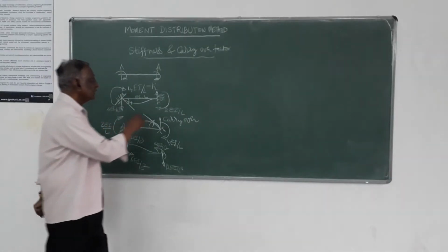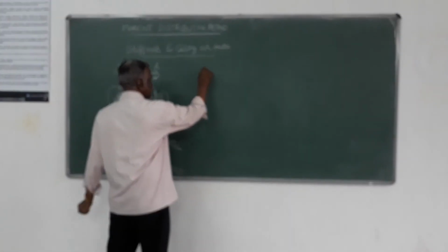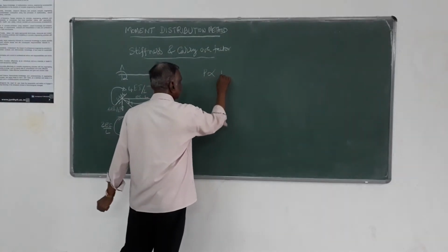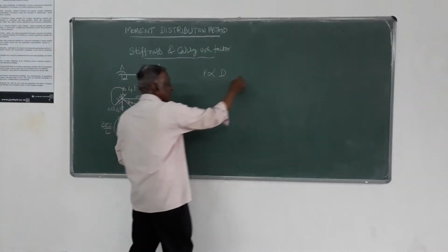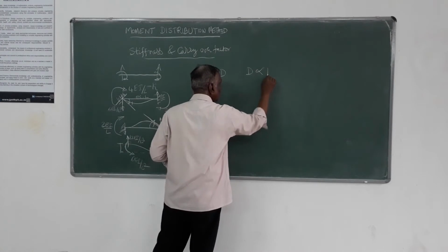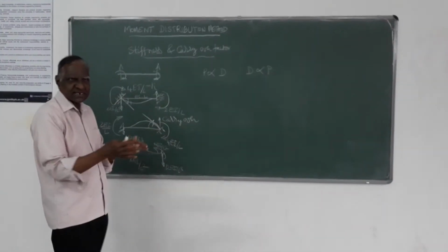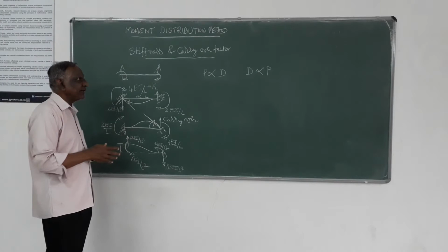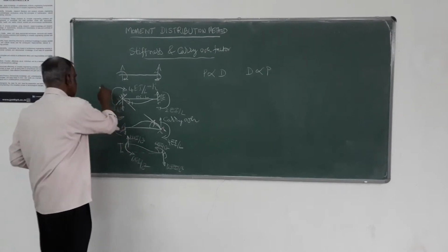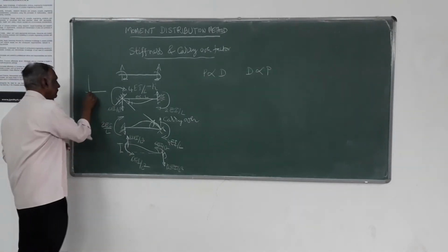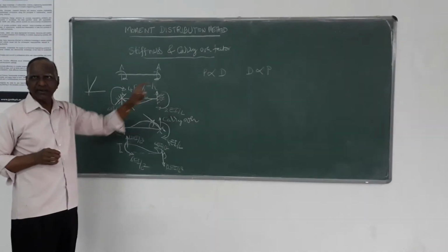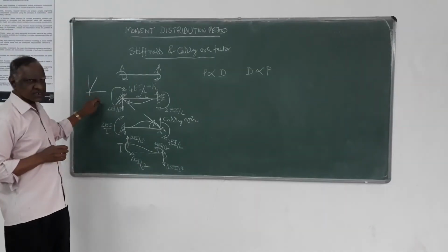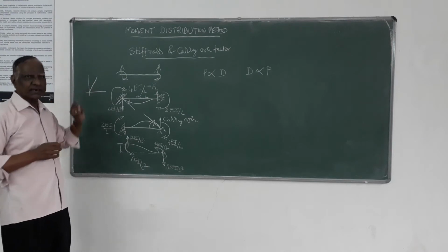So in a nutshell, for the force displacement relationship, we can say force P is proportional to D or vice versa, D is proportional to P, because within the elastic domain or elastic limit, you know the force displacement relationship or stress strain relationship will always be linear. That is, direct proportionality will be there between stress and strain or force and displacement.